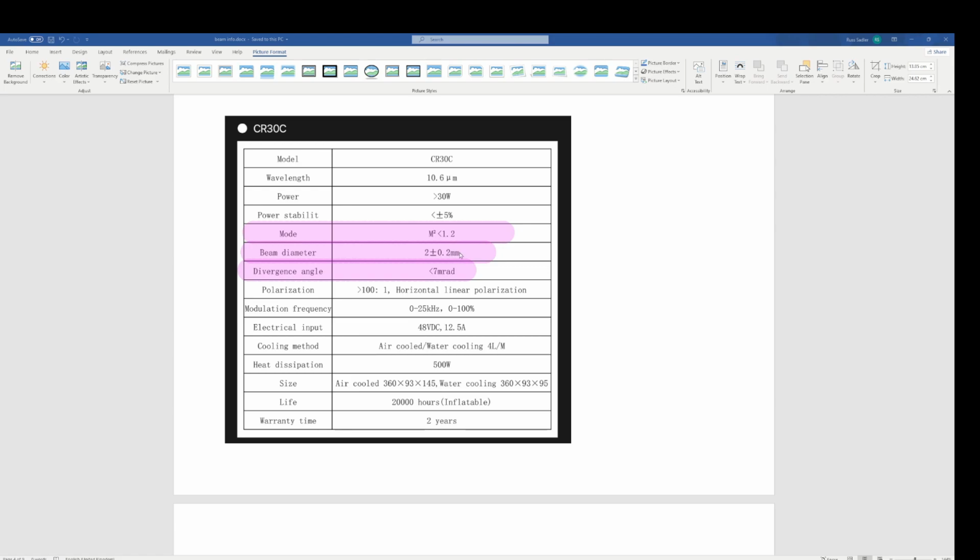It really doesn't matter that it's not a perfect match, because I get this incredibly high intensity, which burns through the material at an alarming rate. Remember, it only took 4 seconds to burn through 25 millimeters, whereas my CR70 tube, with 2.5 times the power, took nearly 10 seconds. But the beam divergence now is 7 milliradians.